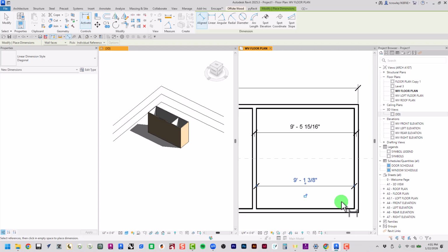So I'm going to choose faces of core. I'll measure from this interior face to this interior face. I get 9 foot 2.5 inches. Let's delete these guys. If I select this wall, and right where it says 9 foot 2.5 inches, just click once, and we'll type in 10 feet. Okay, so now that's exactly 10 feet away, measuring from structure.